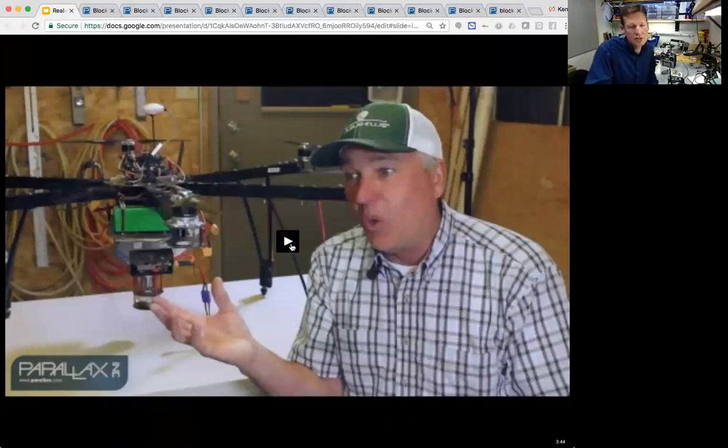So the Propeller has no interrupts. It has 8 processors that run in parallel with the shared system clock. So let's say you're monitoring a button or you're waiting for a serial string to come in, you would just run those in their own processors. And this eliminates the hassle of figuring out what to do when an interrupt occurs and makes your code a lot easier to read.